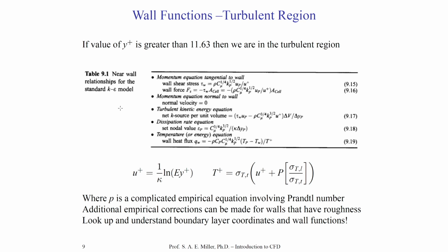This is very troubling because, of course, in certain flows, your boundary layer might transition from a laminar boundary layer to transitional to fully turbulent. So you'll have great difficulty in selecting a single model. Certainly, there are even more complicated wall function models which you can use. Let's look briefly at these types of equations.